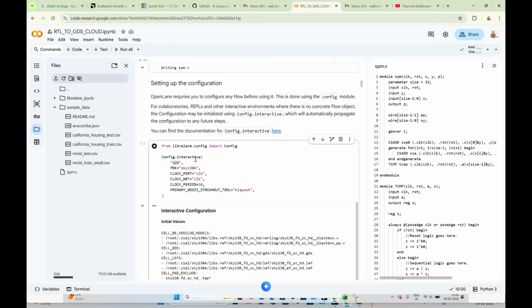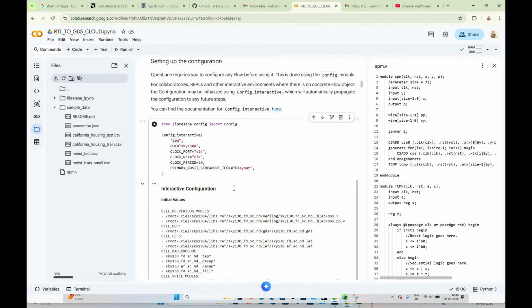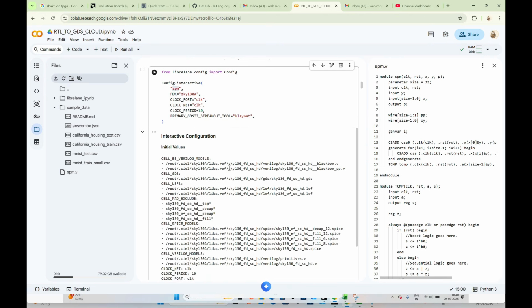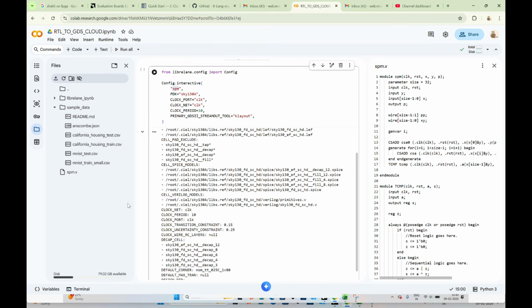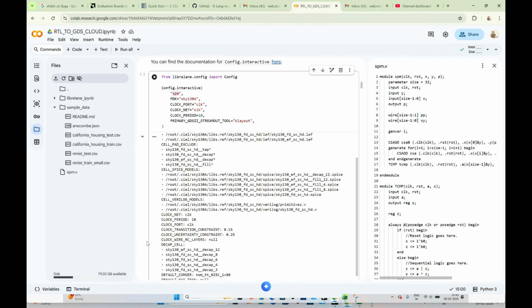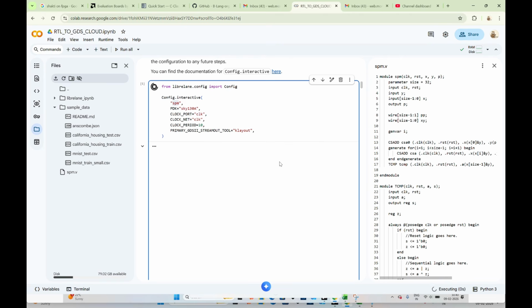These settings are the parameters we use for clock synthesis, timing analysis, and clock routing constraints. Next is scale layout. Next we define the tool with which we will be viewing our GDS. We will be using KLayout for that. Now we have successfully configured our design.